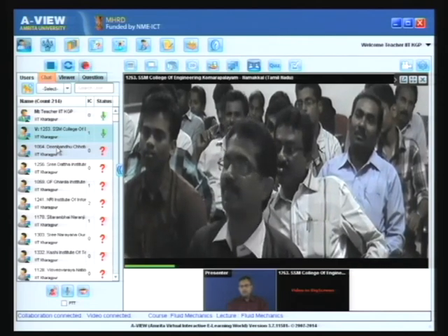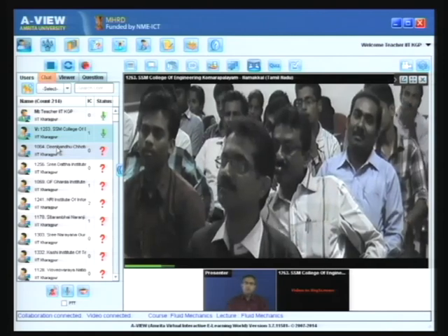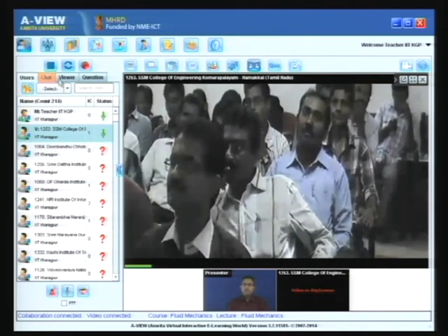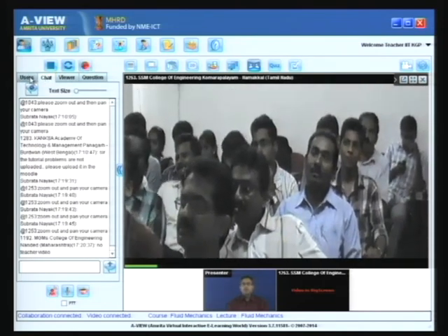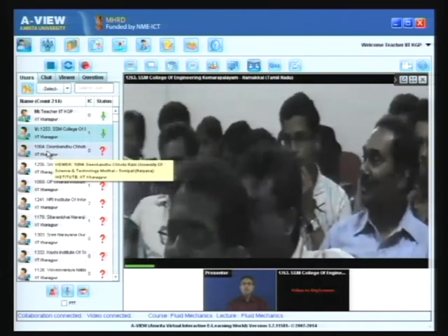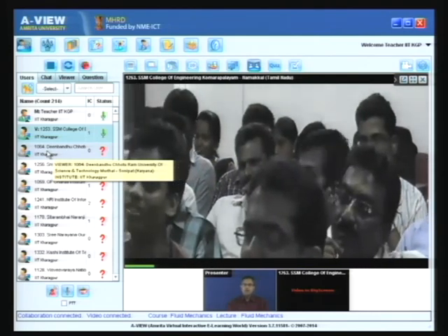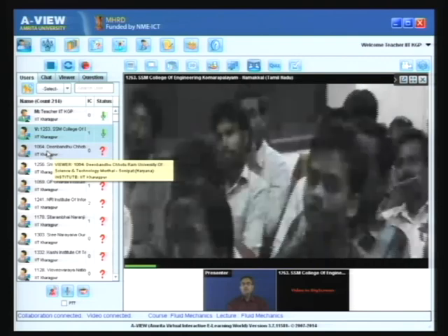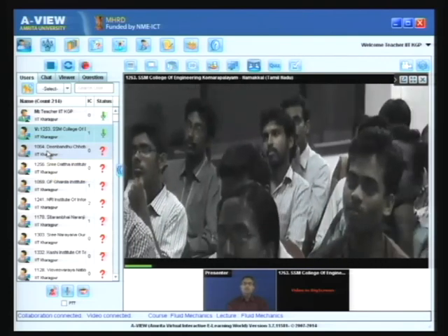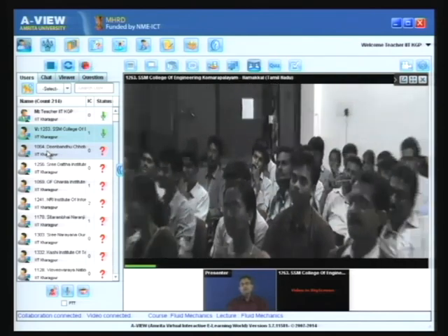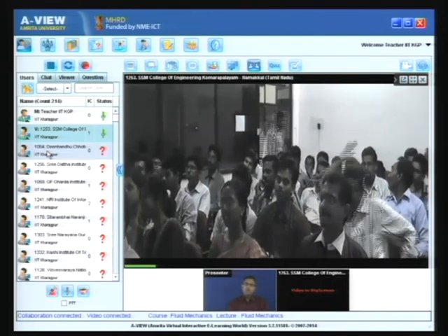See, the thin film flow depends on the film thickness. The problems that we have solved are for a thickness h which is thin as compared to the macroscopic scale, but much thicker as compared to the nanoscopic or microscopic scale. So if the thickness of the film is at the nanoscopic or microscopic scale, then the surface tension forces become important, and the contact angle between the liquid and the wall material will be very important.